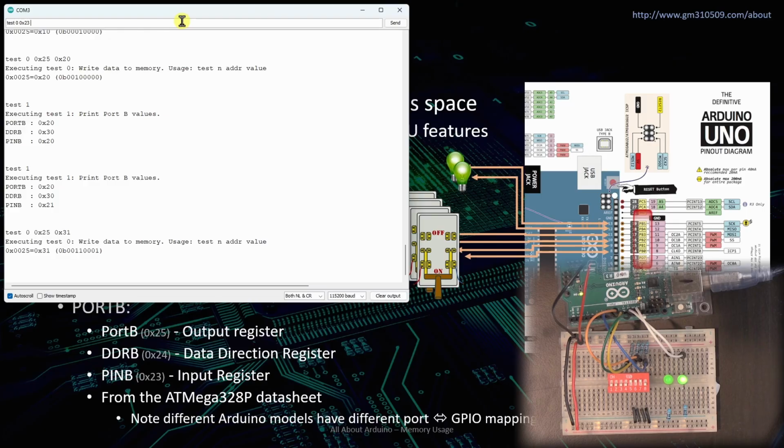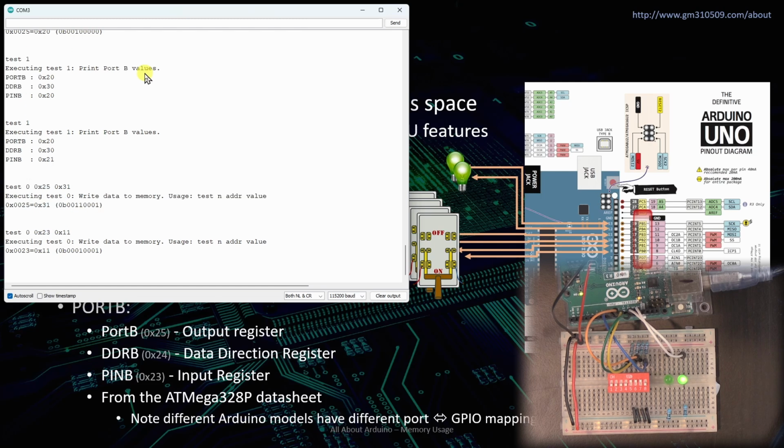And so if I write, let's say 11, then I'm writing 11 because I want to keep this bit as its input, and I'm going to write a 1 to effectively this bit, and then write a 0 to this bit. That's the change. That's the significance. And so what will happen is when I do that, if I write to pin B when it's in output mode, then this is just how I remember it, but the "in" becomes invert, not input. So let's try that, and what we should see is that one of the LEDs will turn off.